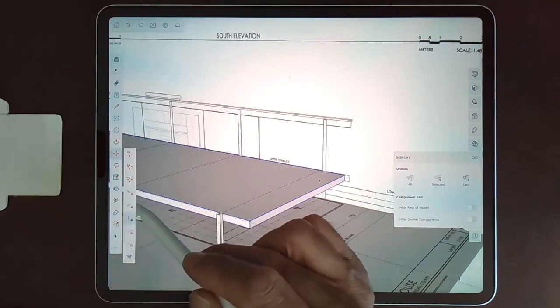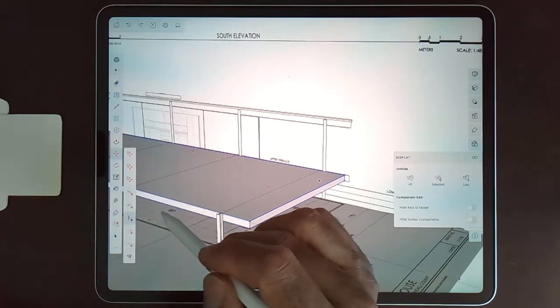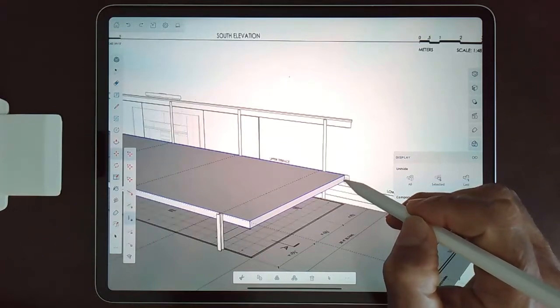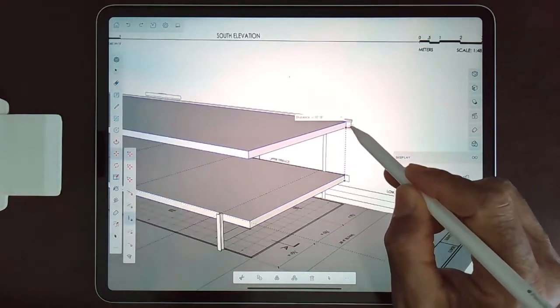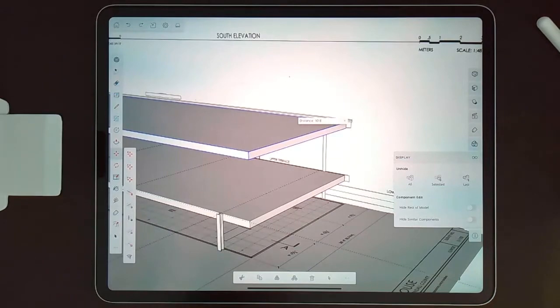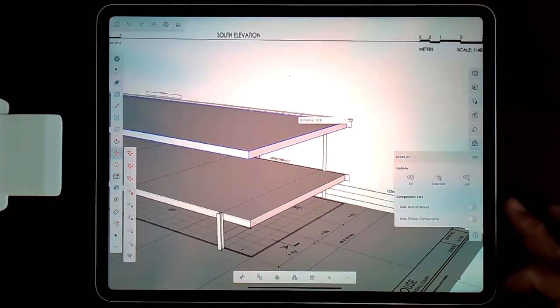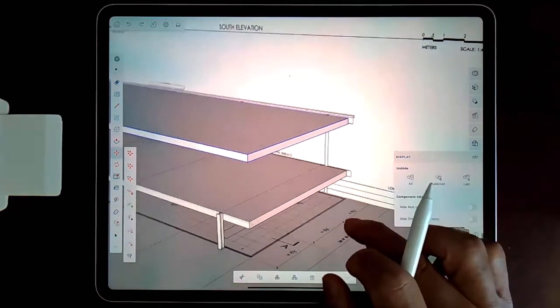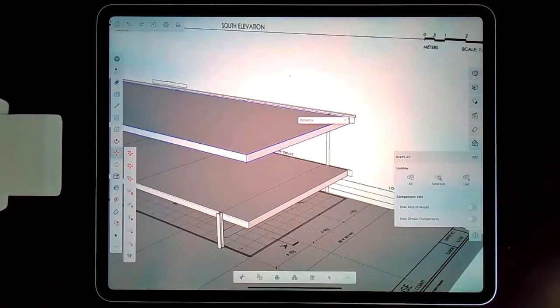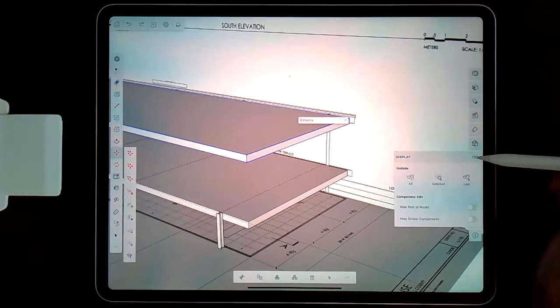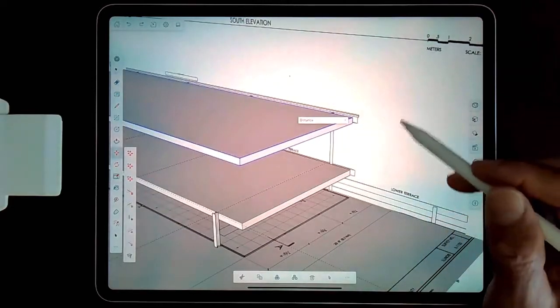And use our constraint tool to maybe take the floor, make a copy of it, to use that as our point of departure for the roof line. So we've now moved that up about 10'6" roughly. And we have to change its thickness. Obviously, we learned that it's a little bit broader, a little bit wider, about 18, 19 inches or so.